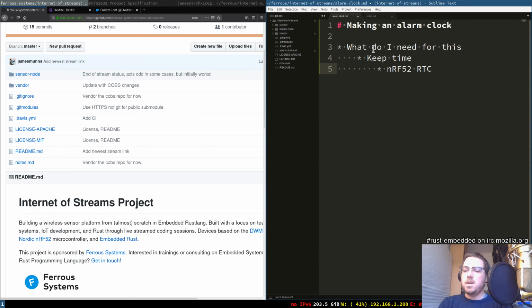So there are definitely different layers of accuracy you can go to here, and I haven't looked at the data sheet for the NRF52 to figure out how accurate it is, but they're typically more accurate than the high-frequency 64 megahertz clocks. So we're already going to be a little bit better than that. They definitely make some that are controlled, what are called temperature controlled oscillators, or TCXOs.